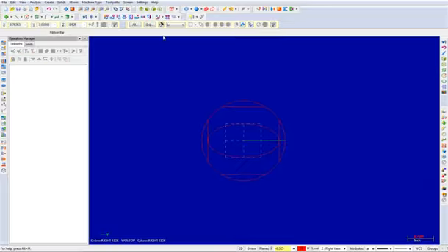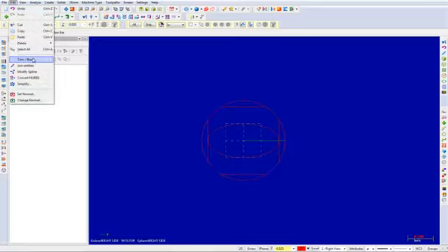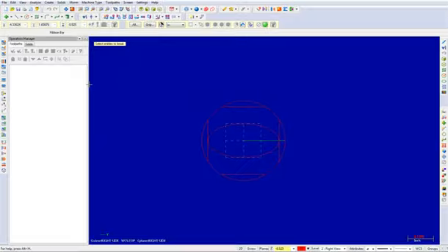Choose the command Break Many Pieces. Select the 4 lines which make up the rectangle and press the End Selection button. The Break Many Pieces ribbon bar will appear. Enable Exact Distance and change the number to 3 as shown. Once complete, choose the OK button.